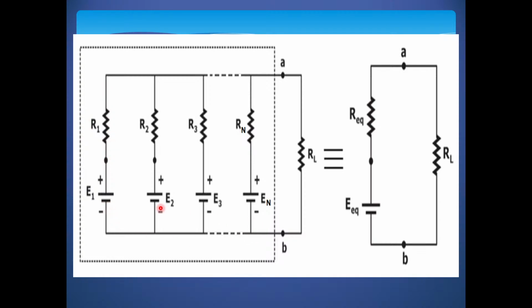When you look at this diagram, it seems as if these are not internal resistances. These resistors R1, R2, R3 up to Rn look as if they are connected in series to the source. Always remember, internal resistances can be represented in series with the sources. Sometimes the question does not draw any resistor in series with the source. If there is internal resistance to a particular source, they will simply mention 20 volts comma 2 ohms. If it is mentioned like that, while simplifying the circuit you can draw a 2 ohm resistor in series with that voltage source.